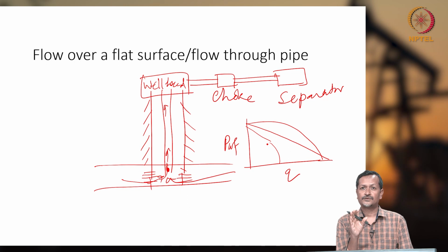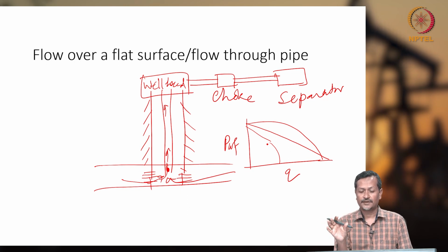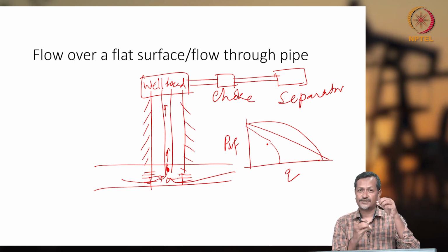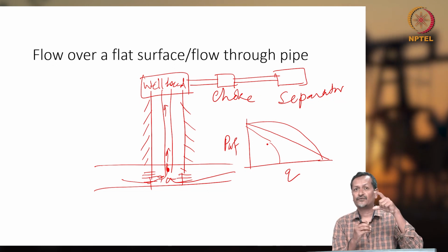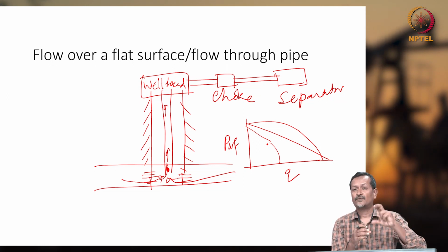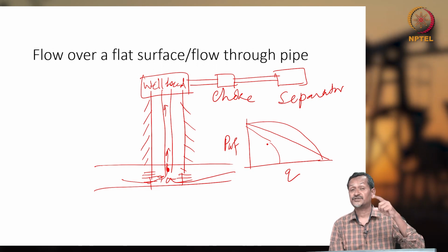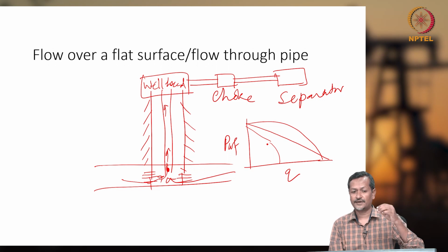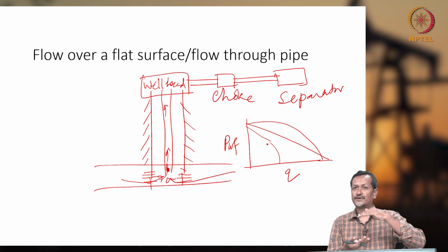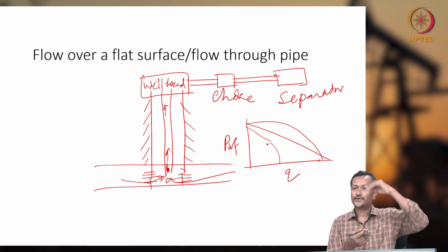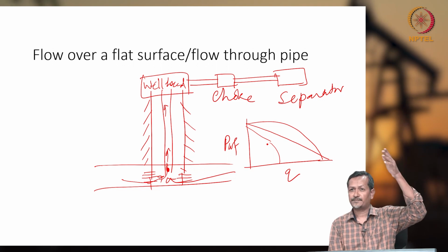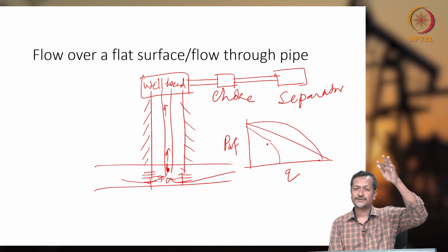So to maintain pressure, you have to understand where the losses are and how much fluid flow there is, what the tubing size is, and how much gas will evolve or come out from the wellbore if pressure changes. For example, if the pressure drop through the piping is very high, the initial pressure may be 1000 psi, and when it reaches the wellhead it may be 10 psi, 20 psi, 30 psi.